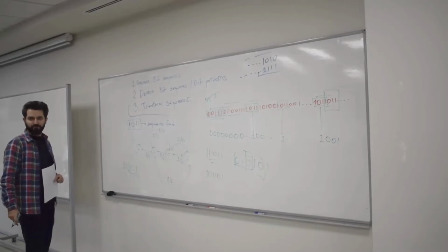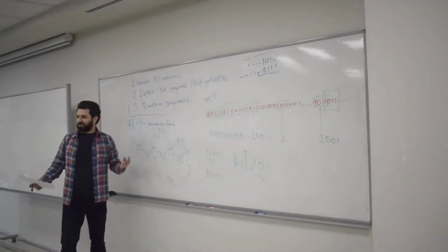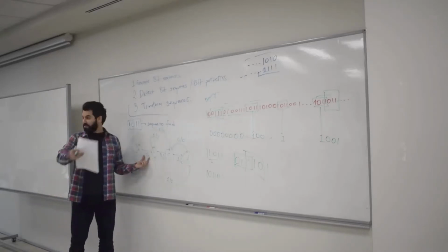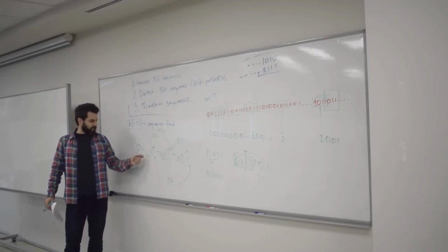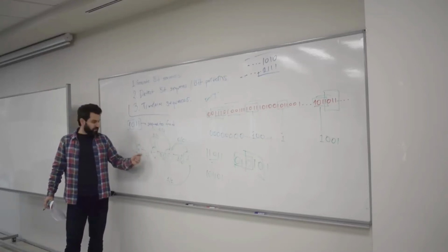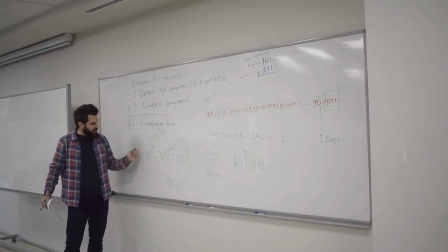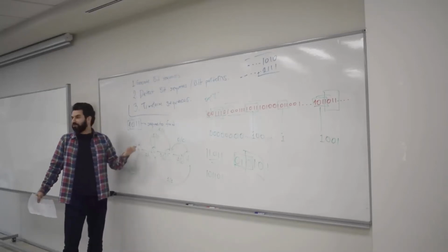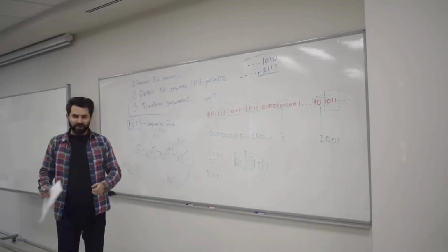What do you think? Mealy, right? Mealy. Why? There are two reasons. First of all, by just looking at the arrows and the input-output relationship, you can immediately say that the output is a function of the input, because it depends on the input. If you don't know the input, you cannot say whether you go from A to B or stay in A. So if there is a dependence on the input, then it's a Mealy circuit, okay?